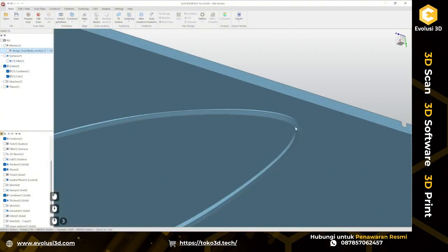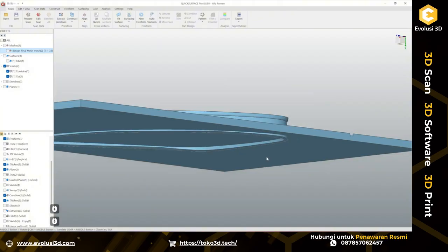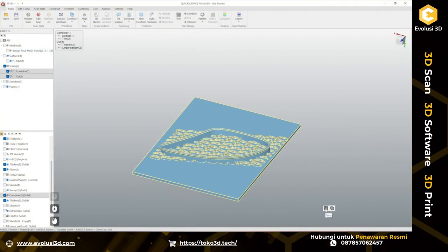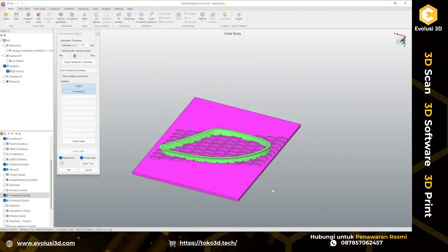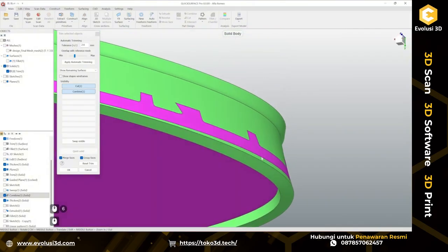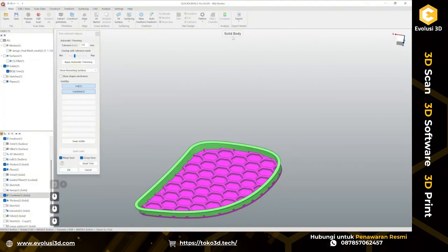After that I created this frame around, a little bit taller than I need, so it intersects completely with my plane here. And at this moment I'm going to simply use the solid trim function, and we'll get rid of the excess of this plane, same as the excess of this frame, like this. So we have a single solid. Let's click OK.